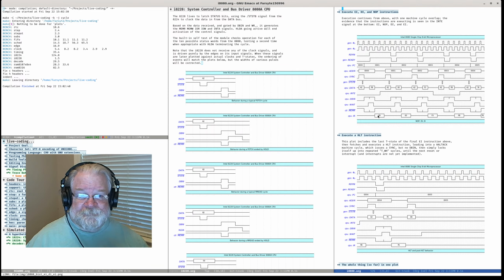the IR here. And we're doing that, well, we have a choice. We can either do that on the rising edge or the falling edge. On the rising edge, we might be triggering before the ROM triggers. So on the falling edge of memr, the releasing edge of memr, which is the falling edge of DBN, we're going to latch the opcode data. So we need to make sure that we latch that before the ROM sets this to high impedance.